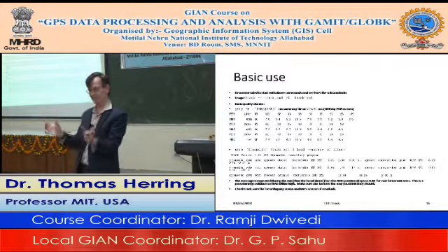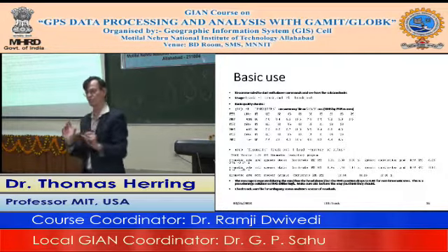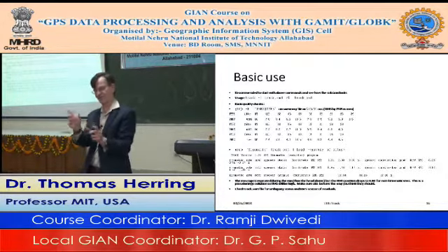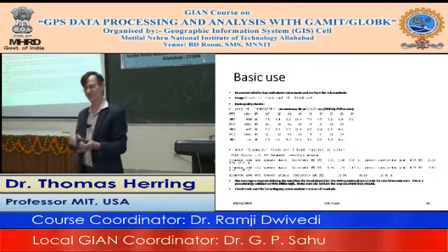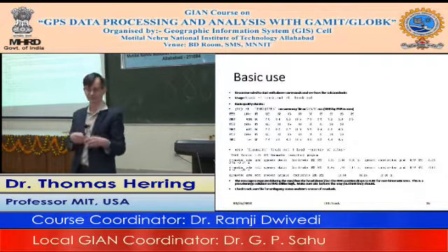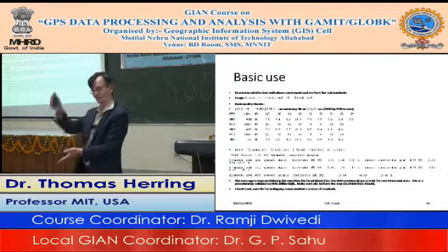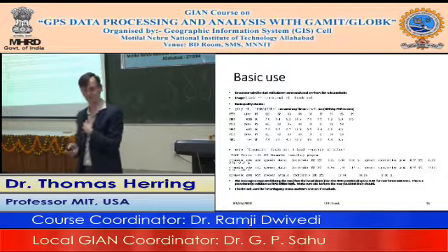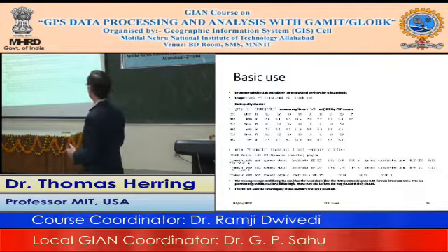So we'll run track telling it that and resolve the ambiguities, then take that ambiguity file and rerun track with it fixed, but now say it can move all the time. The advantage is that the period when it's actually static lets you measure how much noise and fluctuation is in your static solution, so you can interpret the quality with which you can determine the seismic wave arrivals. So this ambiguity file is a very typical way that we generate it.